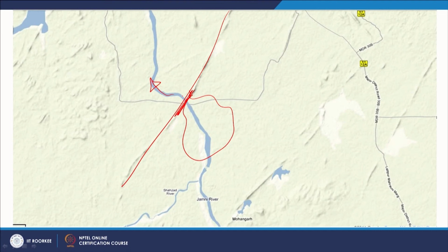Another thing is how to further assess this situation. You remember that we did hydrologic modeling in GIS, and we created a drainage network. While discussing this surface hydrologic modeling, in the beginning I said there is an assumption that each drop of water will flow as surface runoff on the surface. That assumption is okay, we can even exploit it, and without doing much, just by adding one more layer, we can find out which areas will provide better groundwater recharge.